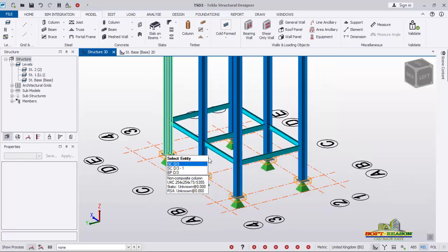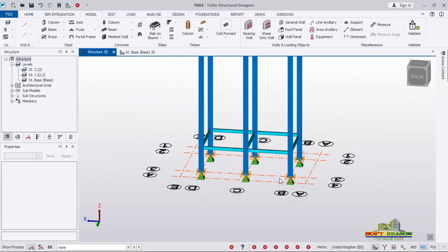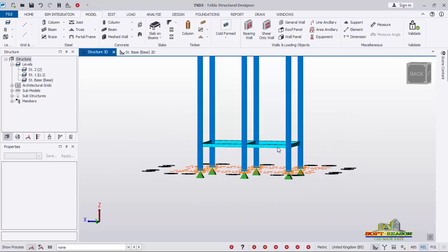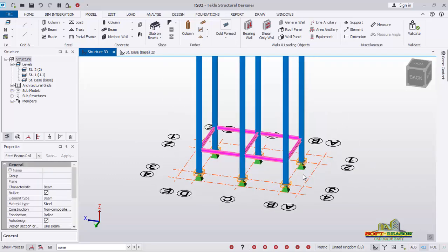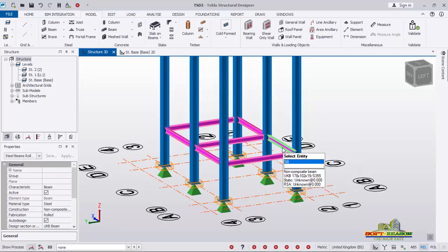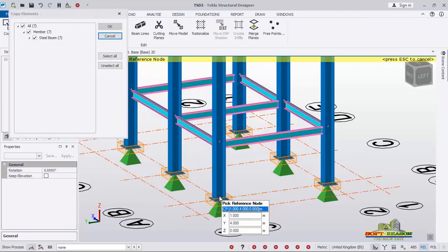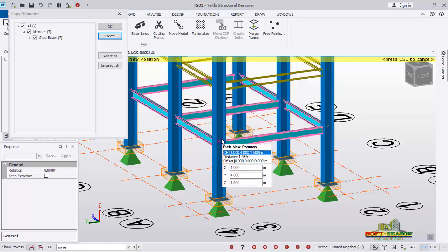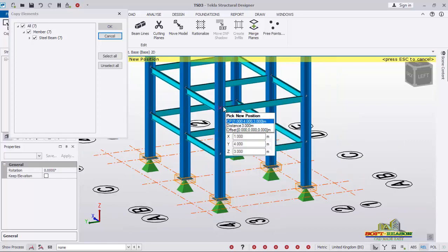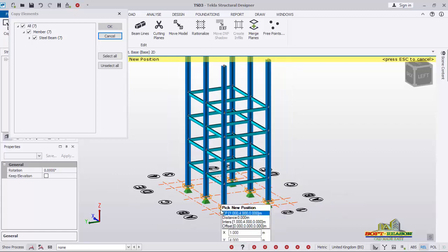All right, so having this successfully, for ease of modeling, you can just highlight all of that. Having all of that highlighted, what you just need to do is go straight away to the edit tab and then click on copy. You can copy that from the base point, take it up, because we will be having an interval of 1.5 meter between the beams, just like that.